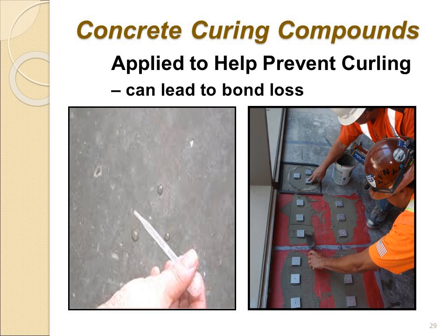One of the things that will change in that practice is when you drop the droplet, it should be within a half an inch from the slab. If you drop it too high, it could give you a false negative because the water will just spread out and it'll look like it's absorbed. So that's one way to do it.